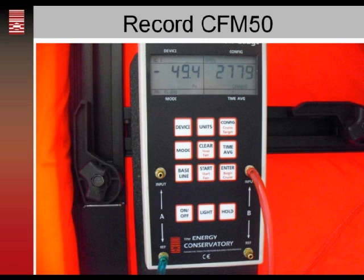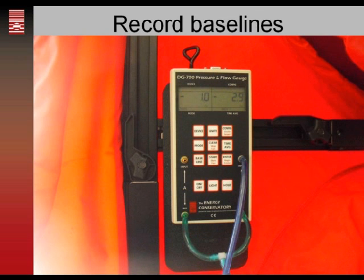First, we'll take our CFM 50. We've got it set to pressure flow at 50 mode. We get close to 50, and we take our CFM 50 number and record that. And these are baseline adjusted numbers. And then in this case, we're measuring attic to outside.